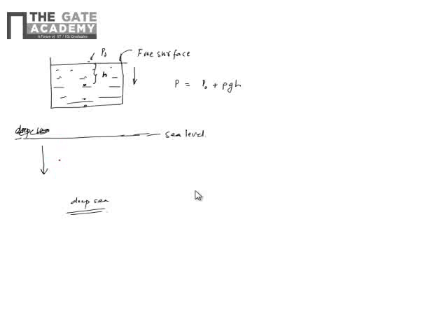So the same thing applies. If you know the height, you can just find out what is the pressure that is acting. So if we have a submarine, the pressure from the liquid, let's say at the depth h, you can just calculate it as rho g h, and now this will exert some net force on the submarine. So all that can be calculated based on this simple equation, how much pressure is increasing as I go deep from the free surface.